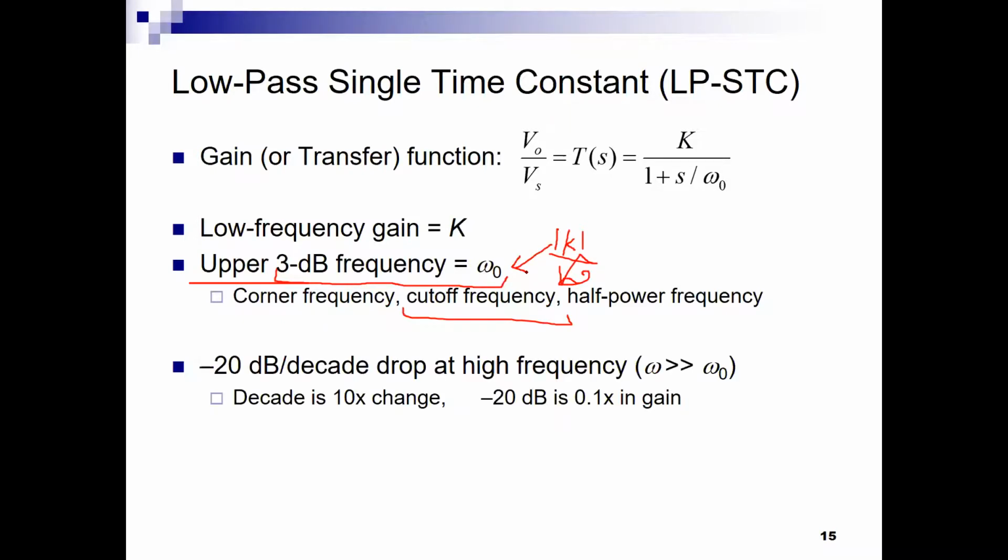And then we talk here about, now we start to explain to you that the transfer function is really going to have a slope. Okay, so we start to talk to you about that the transfer function is going to first start with a constant gain, and then the gain is going to drop.